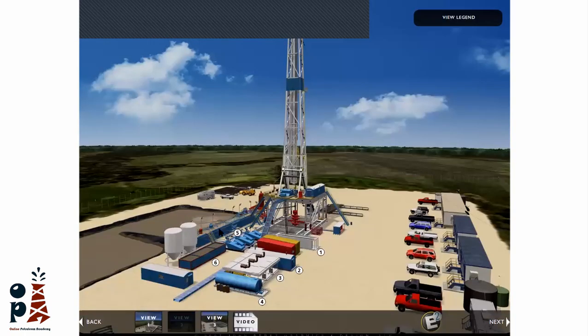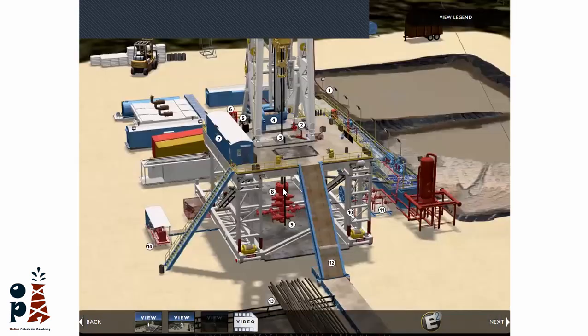Here you can see from this view the tanks, and you will find the rig pump. Okay, you will find the waste pit, which is just below the shaker area, so that we can receive the cuttings in this area. Also from this view, you will see the BOP. It's here. The BOP is the blowout preventer, and this is the second barrier if we have any kick situation or blowout.